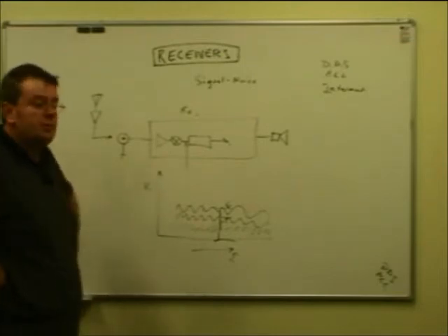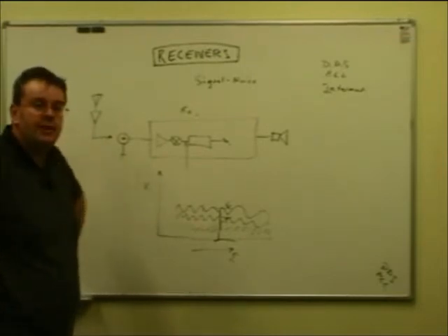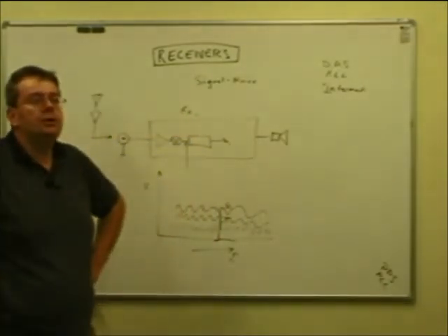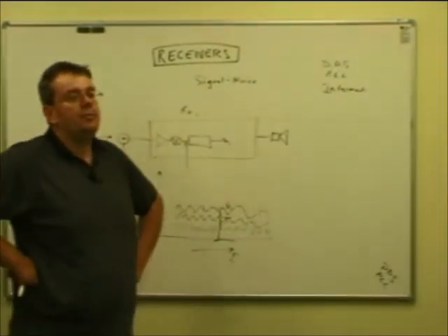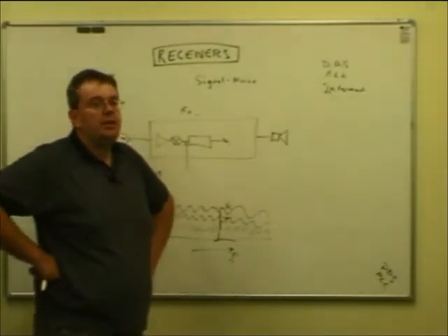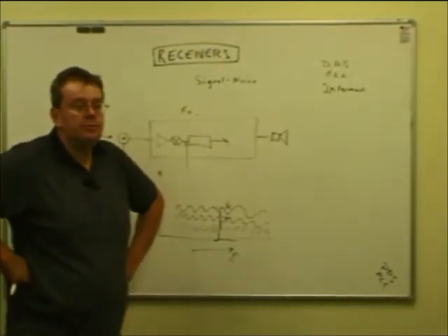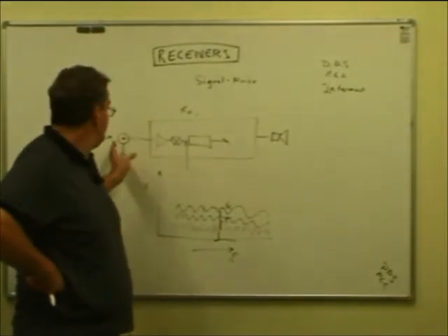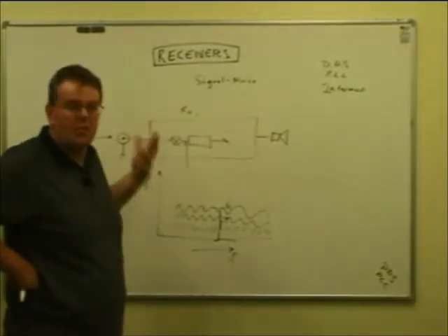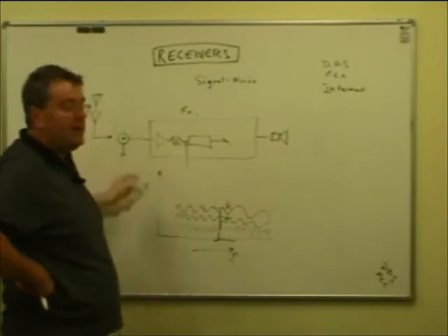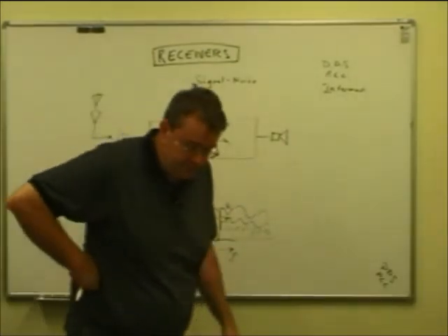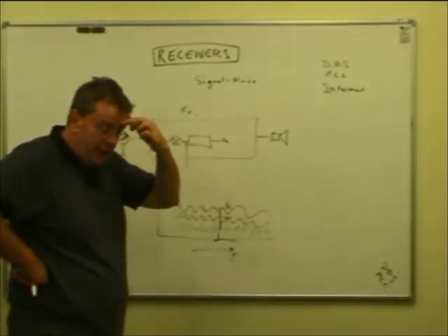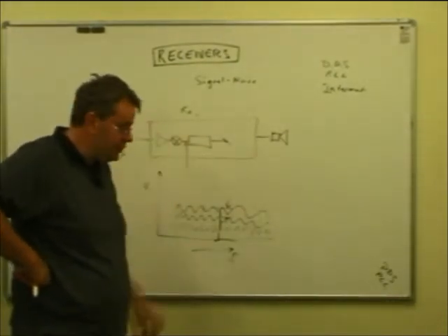So what people will do is they'll put an amplifier right up by the aerial. And that's the same with TV. If you're in a weak signal area and your TV receiver is a long way from the aerial and you want to put a booster amplifier in, you don't put it at the back of the TV set, because your signal's noisier there. All you're doing is just amplifying a noisy signal. If you can put the amplifier up at the aerial, and that's why they make them waterproof, and you can have arrangements to feed the power up the aerial cable to them.